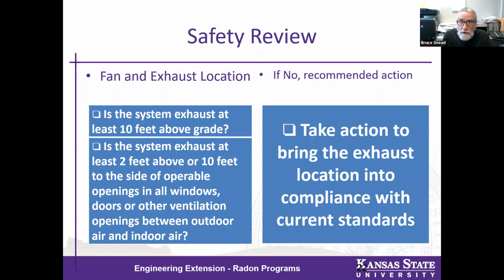Does the system exhaust at least 10 feet above grade? Is it at least 2 feet above or 10 feet to the side of any operable opening to the interior of the home? And that would allow ventilation. And this is a common concern. If not properly located, the action or recommendation would be to bring the exhaust into compliance with the standard.